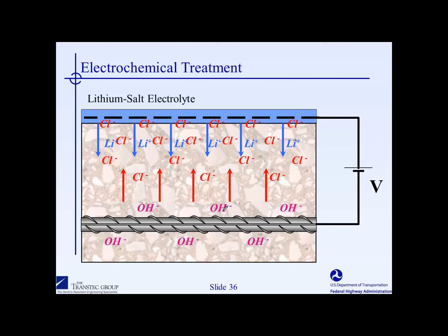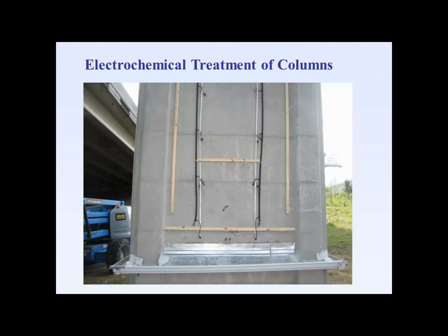But it should be mentioned that these efforts primarily were based on driving chloride out of the bridge deck. Our goal in the Houston trial was there were no chlorides involved. Our only goal was to try to drive lithium into the concrete, and I'll show you how we did that in just a second.